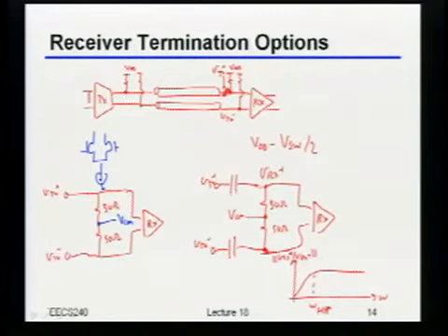Come bug me. But basically, bottom line, your data better be DC balanced. In fact, it better be so-called DC balanced over some number of bits that corresponds to where this cutoff frequency is. So in other words, if this cutoff frequency was at, let's say, 10 megahertz, then you better make sure you can't ever have a long sequence of all zeros or all ones that in time is long enough to span 10 megahertz. Okay, because you'll start losing that data.